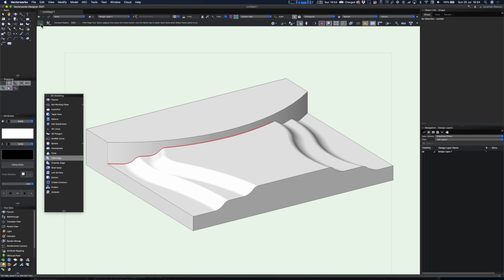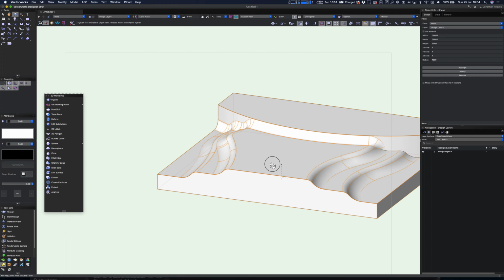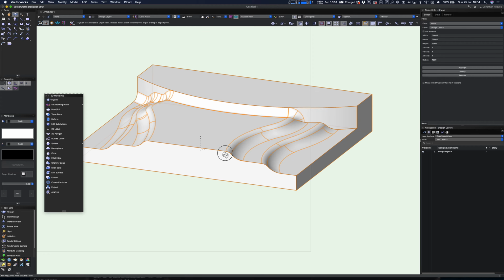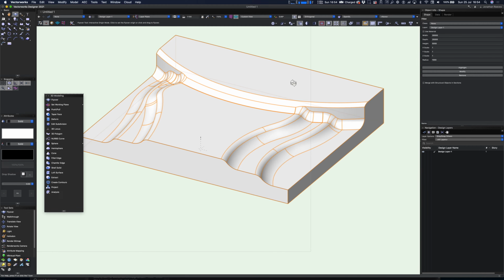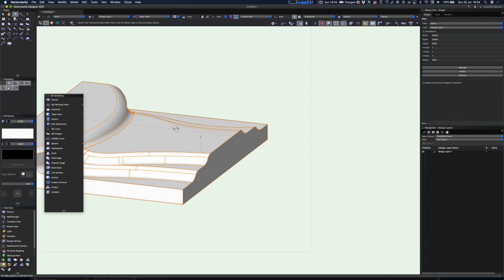Let's click tick, see how that works there. You can see the bit that wasn't filleted, but that's no problem at all. Just click modify, that goes back in, hold shift down, select the additional edges, and when you're ready, hit return or click the green tick once again, just to reapply that fillet radius, and just do that final little touch there.